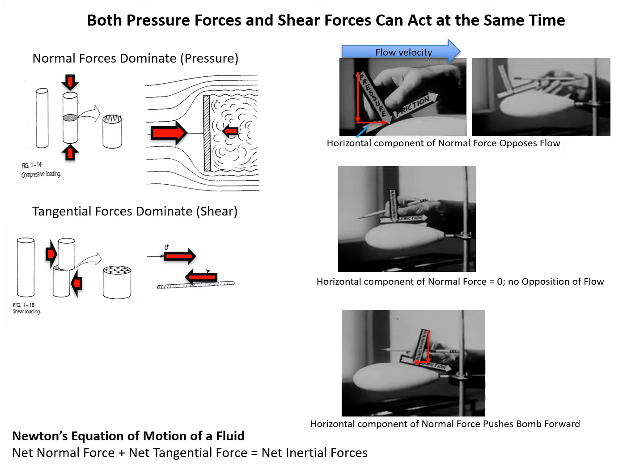If you turn the plate on its edge so that the thin side is facing the flow, then there's a lot of this friction or tangential shear stress induced in the layers of fluid as it flows over it, but almost no pressure force, right? Because the profile facing into the flow is so small. So if you look at, and this comes from that second video on drag that is on Canvas.